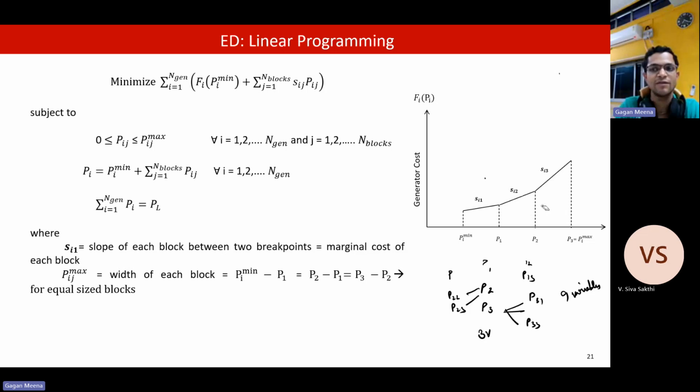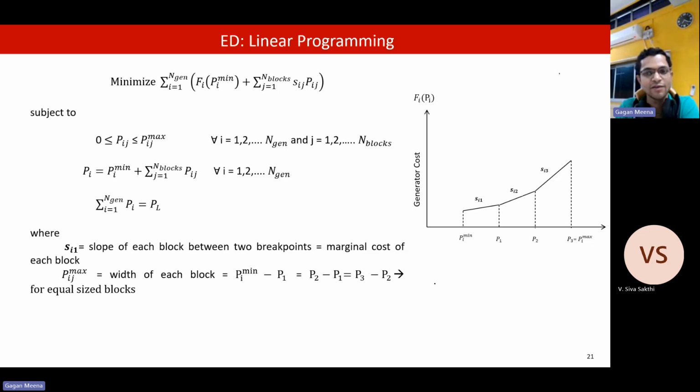This is without network. Now, if you want to include network, then two more types of equations will be added, but the number will depend upon how many lines or how many nodes there are. One will be KCL and another will be KVL. So KCL says that whatever current is entering should leave, right? Entering current should be equal to the output. Here, same thing, we can expand it to power also. At any node, what is the power injection and what is the withdrawal?